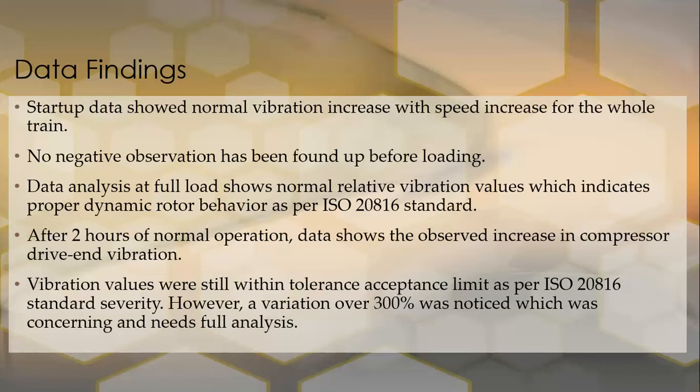After 2 hours of normal operation, a sudden increase in the vibration values and an abnormal noise occurred, which was odd. Although the vibration values were still within tolerance and acceptance limits as per the ISO 20816 standard, a severity variation of over 300% was noticed, which is concerning and needs full analysis.